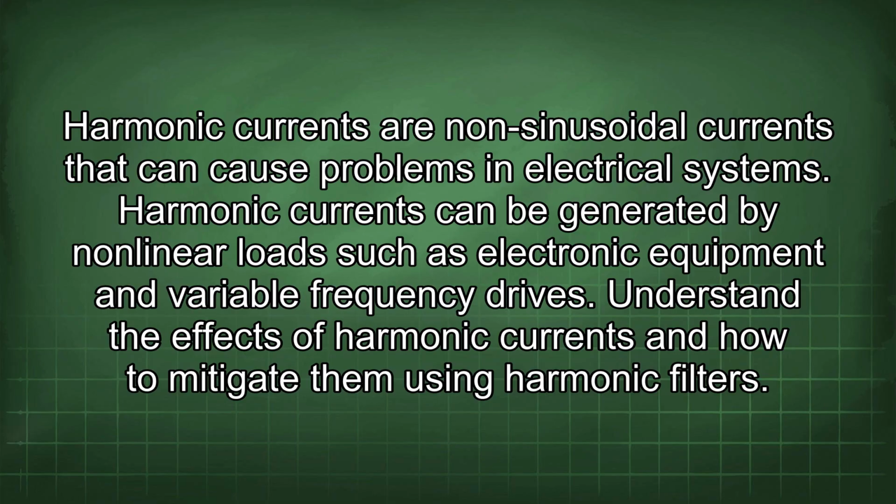Harmonic currents are non-sinusoidal currents that can cause problems in electrical systems. Harmonic currents can be generated by nonlinear loads such as electronic equipment and variable frequency drives. Understand the effects of harmonic currents and how to mitigate them using harmonic filters.